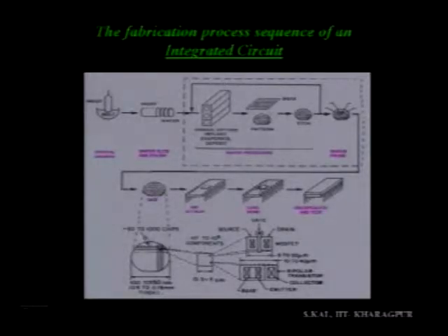So the whole wafer here, you can have at the same time millions of transistors in the big wafer, say 8-inch diameter wafer. Now separate each transistor or each IC, and each IC is then called a dice. This dice is attached on the die attach. This is the housing. And this small die, what you get from this wafer, is of dimension say 0.1 to 1 centimeter, and in this IC 10 to the power 3 to 10 to the power 6 or something like that is components. Nowadays VLSI you can easily fabricate.